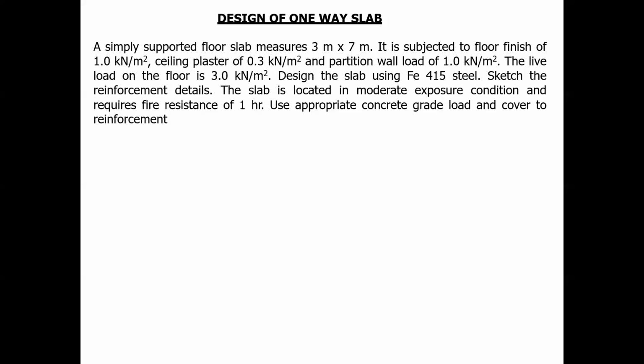And what about fck, grade of concrete? Use appropriate concrete. So here they have not given the grade of concrete. If this type of condition comes, you have to consider M20 grade. Minimum grade is M20. Okay. Take down.